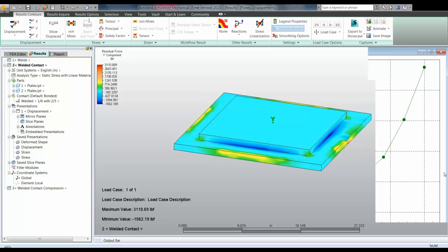When I performed weld analyses, I would like to run a simulation to connect the nodes at the location of the weld, and then select these nodes in the area of the highest value divided by the approximate length to obtain the force per inch. Then I refer to the AWS welding code to see if this was acceptable. Does this sound like a good approach?